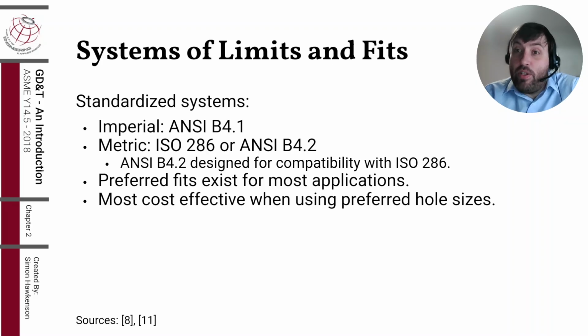It's also very, very strongly recommended to use the preferred hole size, although it's not required, as those use standard drill bits, and they don't require extra operations that would drive up the costs. This really helps to keep machining costs in check.